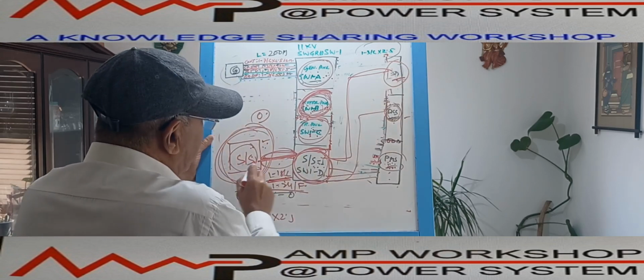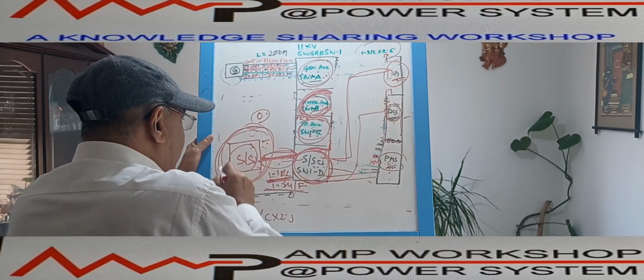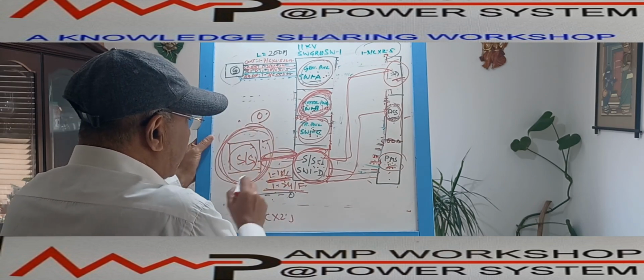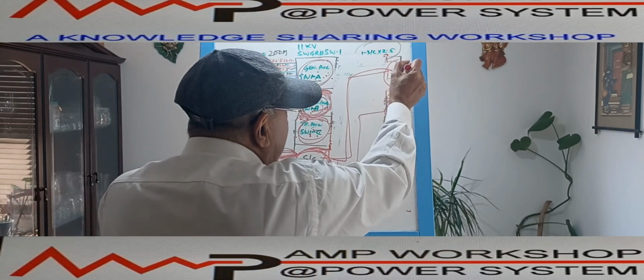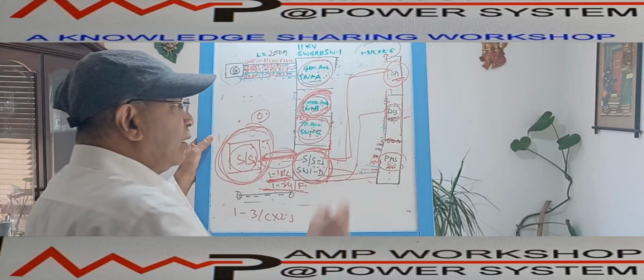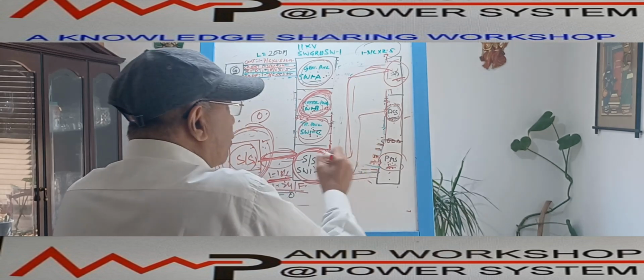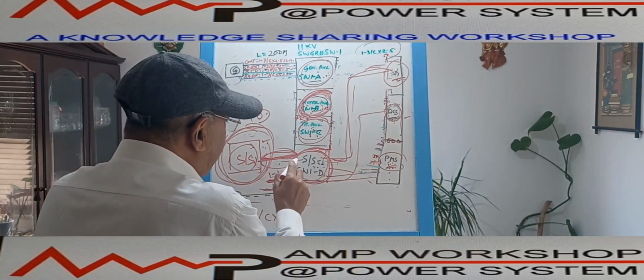The interface will be coming through directly. But if this ESD system over here or the fire and gas system over here sends the trip command through the fiber optic cable to the local ESD system, then through the local ESD system it should be tripped. So there could be one cable from here to here, or a single cable will carry the signal.